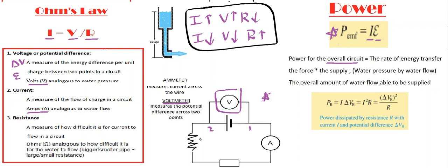which if it was to be drawn would look like this, we wanted to find the voltage, because what if this resistance has a high value, then that means our voltage would be less and our current would also be less at that point. So you could find the power at a certain resistor by multiplying the current and potential difference at that specific resistor. Now what if you aren't given the voltage for that resistor? Using Ohm's law, you can rearrange your variables and find that V is equal to I times R, giving you I squared times R that we see here.